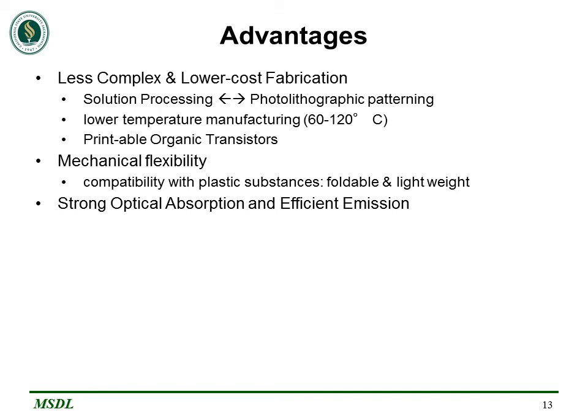There are many advantages of organic field effect transistors, which are as follows. It is less complex and lower cost fabrication. It has mechanical flexibility as it is compatible with plastic substrate, as plastic substances are foldable and lightweight. Moreover, it has strong optical absorption and efficient emission, which can be used in organic LEDs.